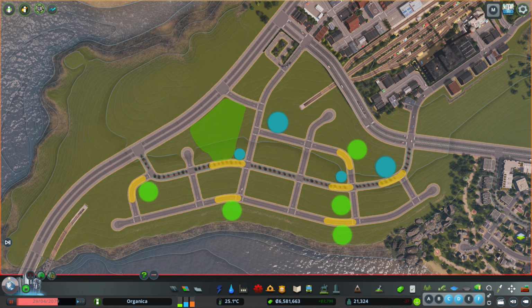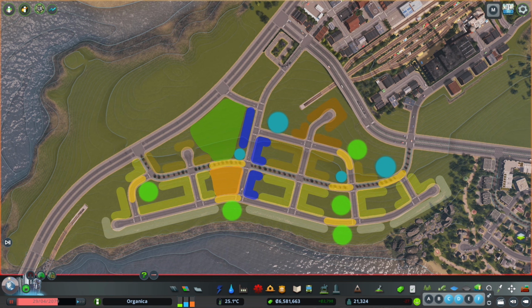At the central point of the area, there will be a square that will connect the neighborhood park to the coast. The commercial areas will extend perpendicularly from the center to the coast, dividing the area into two. I have divided the residential areas into 4 tiers based on building heights. The first tier, with the lowest building heights, will be located in the areas closest to the coast, where the elevation is the lowest. Following this logic, we will plan the other residential areas based on the elevation increase.